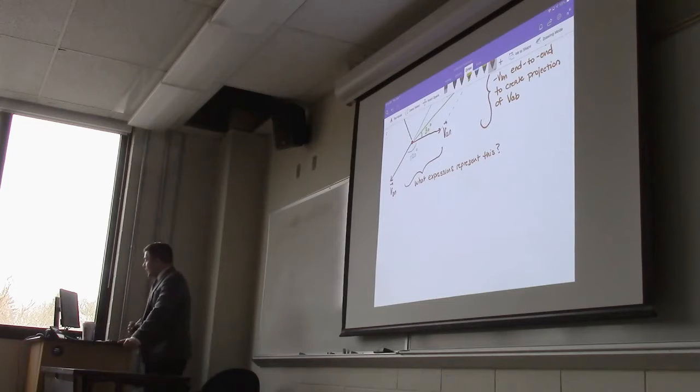These are the conversions that are going to be most useful to you. So VAB is equal to square root of 3 times the magnitude of VAN shifted by 30 degrees.